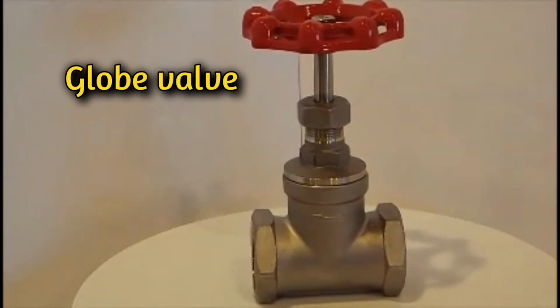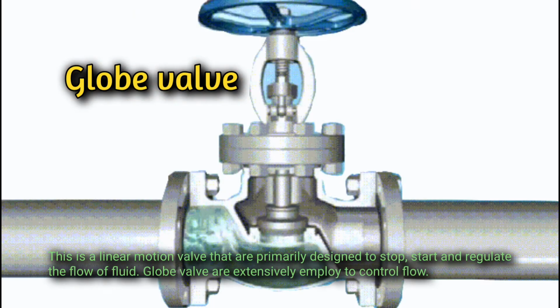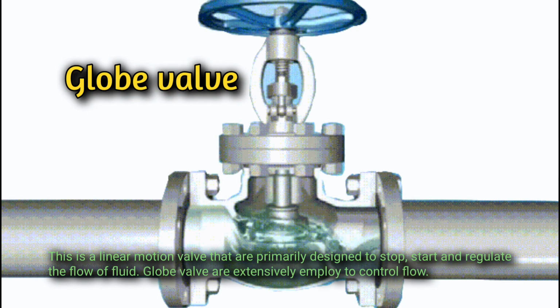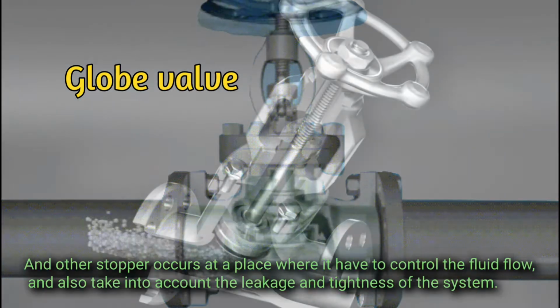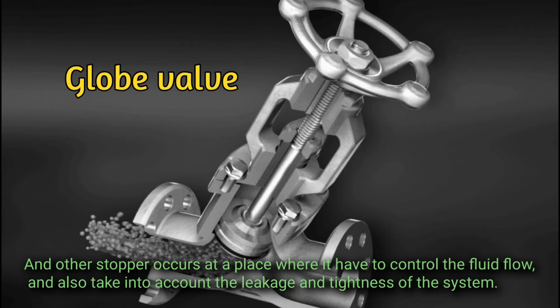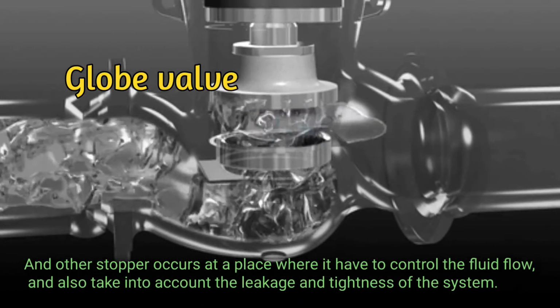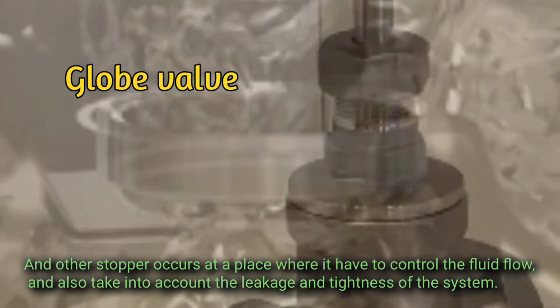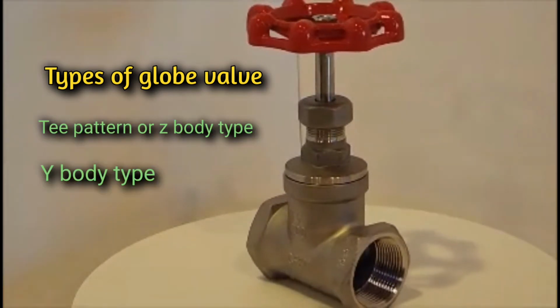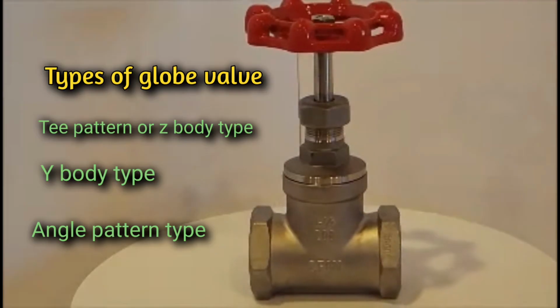Globe valve. This is a linear motion valve that is primarily designed to stop, start, and regulate the flow of fluid. Globe valves are extensively employed to control flow, and in places where it is necessary to control the fluid flow while also taking into account the leakage and tightness of the system. There are three types of globe valve: T pattern or Z body type, Y body type, and angle pattern type.